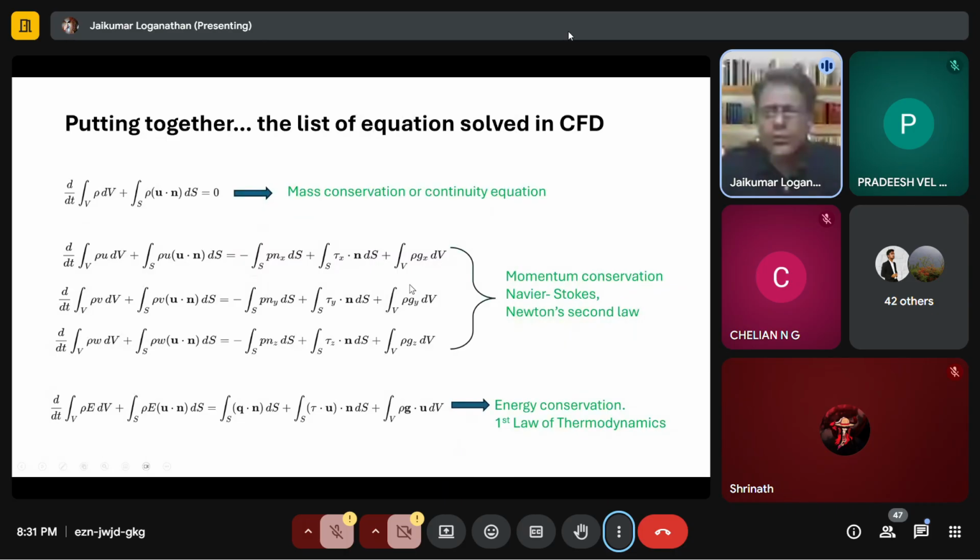We will introduce a few turbulent terms here, and then we get two additional equations, which we call the turbulent kinetic energy and the turbulent eddy dissipation rate, or the k-omega equation or k-epsilon equation. But they are derived from your momentum equations. So keep in mind we usually solve these five conservation equations in a CFD solver, and the momentum equations are called the Navier-Stokes equations.